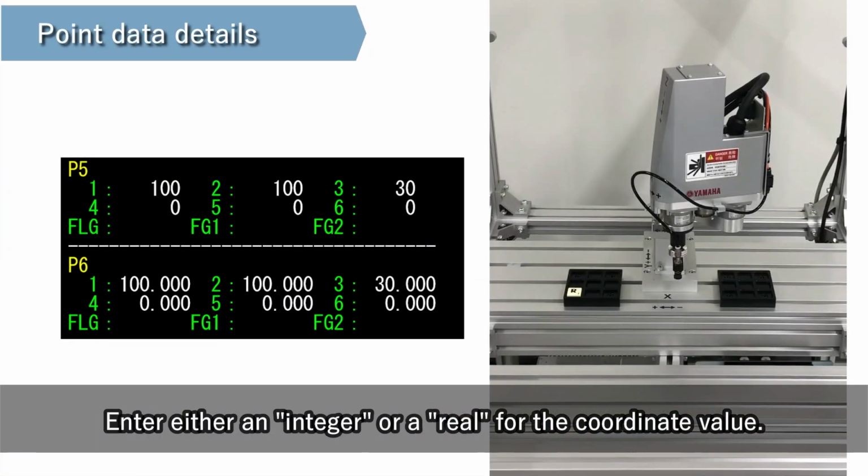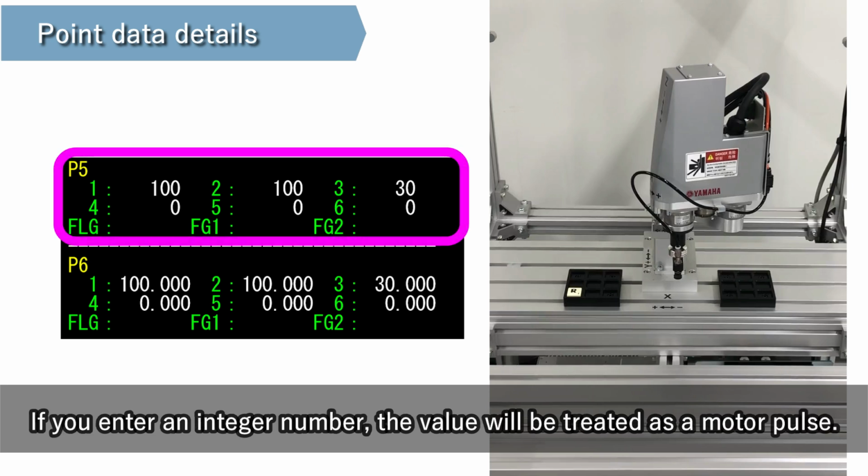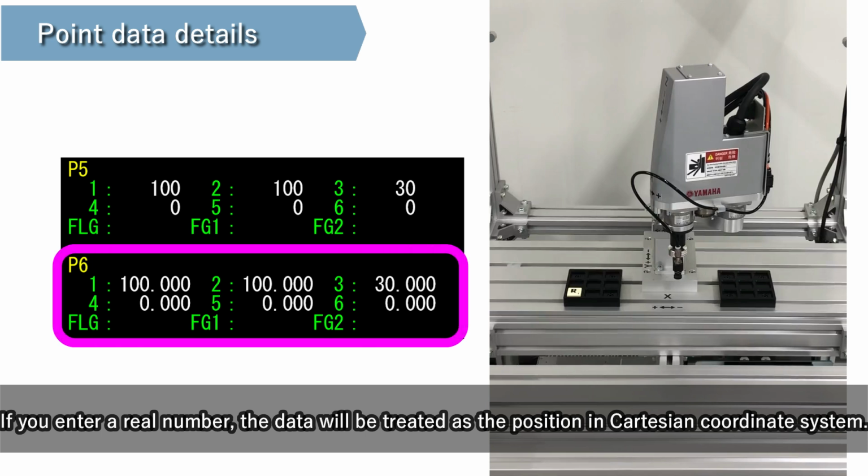Enter either an integer or a real for the coordinate value. If you enter an integer number, the value will be treated as a motor pulse. If you enter a real number, the data will be treated as the position in Cartesian coordinate system.